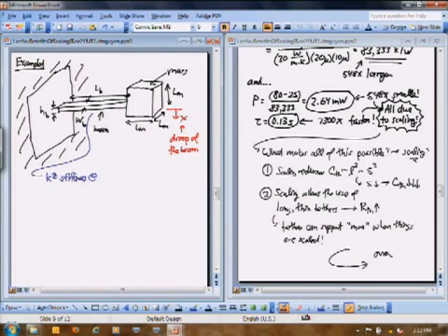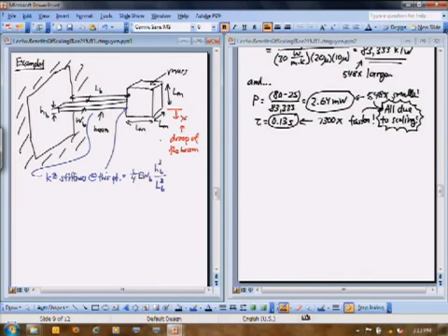And that stiffness is going to be given by the equation which we will derive later on, 1/4 times Young's modulus, which you've seen before, times the width of the beam, times the thickness of the beam cubed, divided by the length of the beam cubed. And that's it. Okay? And so I should say this is a stiffness in the X direction, since I called the downward direction X in this.